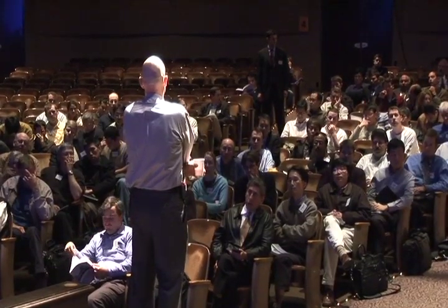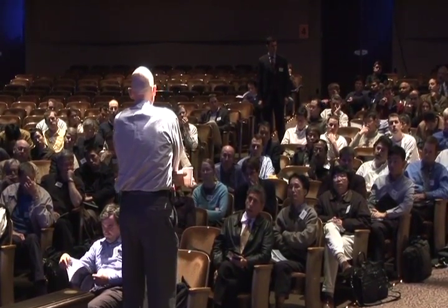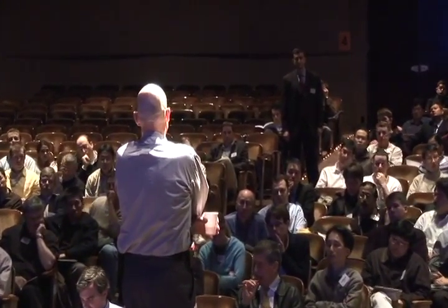Okay. For a chord rotation model. Not the case for steel, though. Pardon? It's not the case for steel. No, the reason is that the capacities given for the chord rotation model in ASCE 41 are plastic end rotations directly. And it turns out they're the same as plastic hinge rotations. In fact, the FEMA beam model in Perform actually converts to a plastic hinge model. But in a steel beam, there are multiples of yield, so it's not simply taking the same capacities and transferring them. It depends on the aspect ratio of the beam.